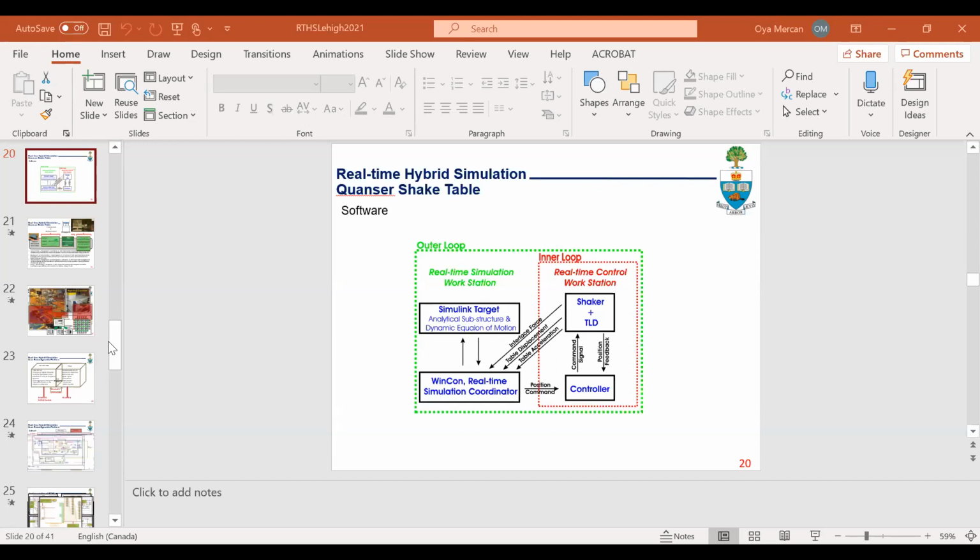Right. In my experience, I could maybe give a little bit. The number one thing is synchronization of your signals. So time delays are very important. Sometimes you need to extrapolate feedbacks so that they align properly. So you want to make sure that you're using a sample rate that's very small so that you don't create any numerical errors. And then also, two other things are your solver. What kind of explicit or implicit algorithm are you using? Typically, explicit algorithms might be better. And then, finally, you could even look at damping of the overall model. Sometimes increasing numerical damping will produce a more stable system. So again, from my personal experience, I hope that helps.